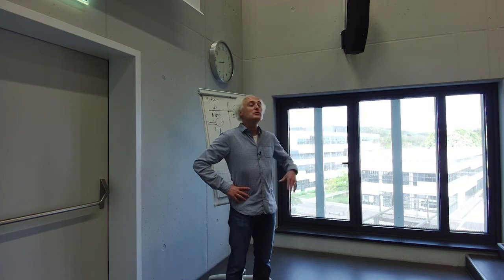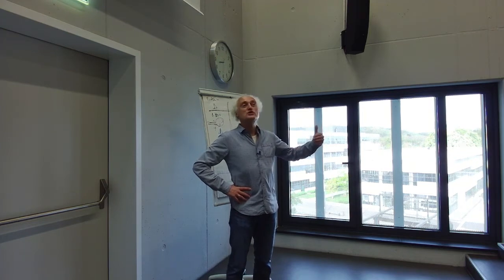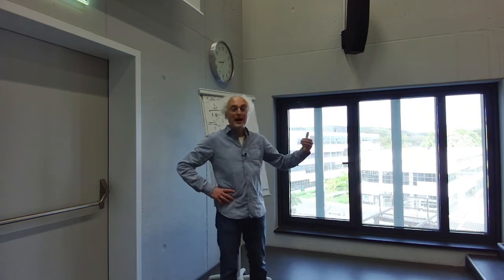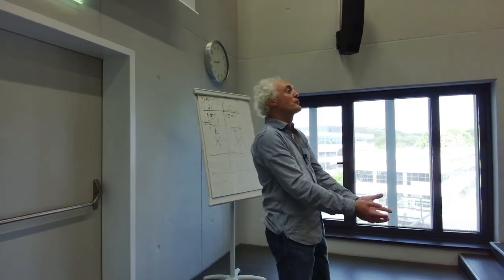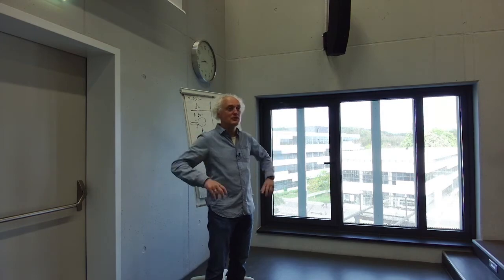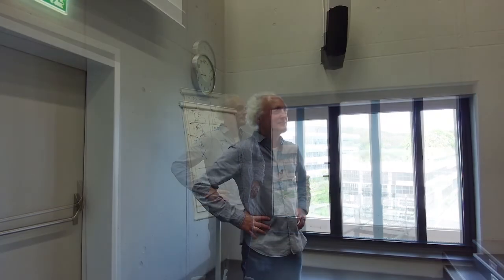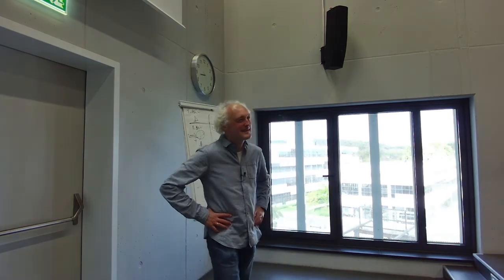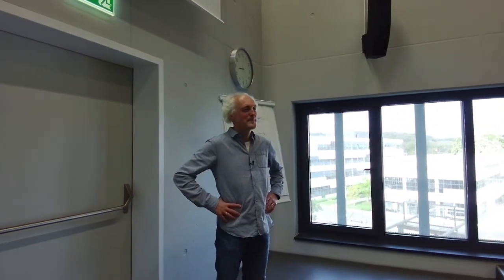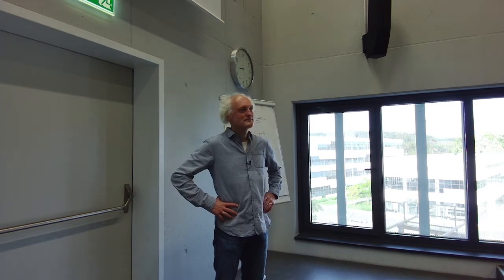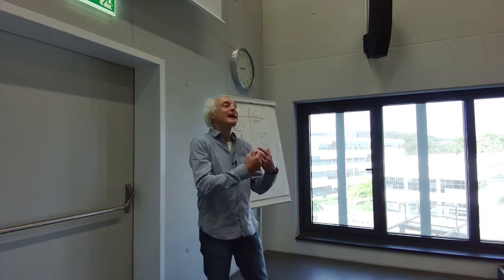So normally the biomass is not what you want to have. Yeah? Let's assume it's not the biomass you're interested in. You produce, for example, a metabolite or something like that. Yeah? So is then the growth rate, the specific growth rate, the only relevant thing? Well, if we don't excrete our product, the growth rate is actually kind of important, because otherwise it would take quite long to get your final product. If you excrete it, though, it's kind of negligible. Exactly. So it kind of depends.